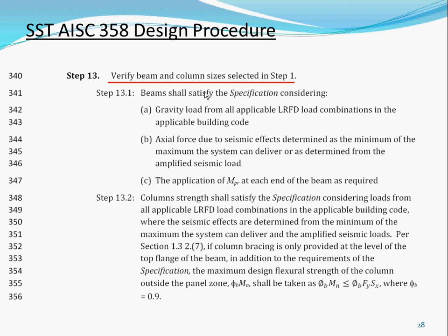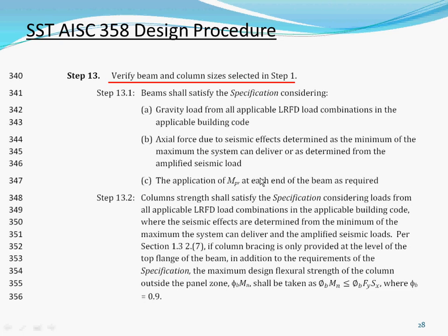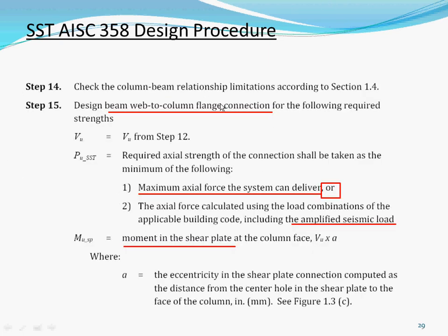Now we want them to go back when they size the beam and column, and previously they sized the beam and column just based on the link elastic. So now the next step is we want you to size the column and then the beam, assuming yield, assuming the worst condition, assuming the ultimate, which is at the top of the curve, for that force. Instead of elastic force, we want you to check it at the ultimate force. That's why this is an extra step check for that force. Okay, so then check the beam, check the column for those 2 steps.